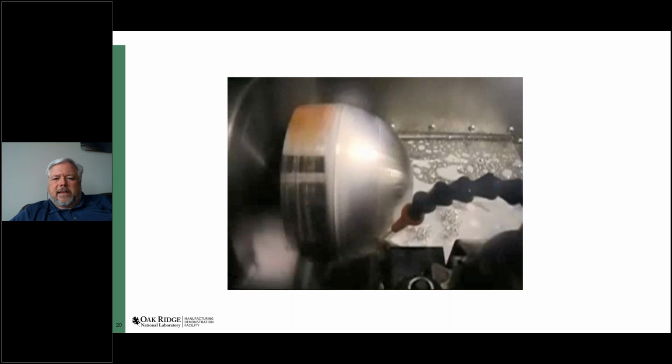Okay, so now what's the price that I pay for this, right? The NC program is getting a lot longer, right? If it was just turning on the outside of a workpiece, you know, it would say move the x-axis from here to there, and it's one line of code. And instead, I'm putting in lines of code that specify the motion of the tool back and forth. And so the program got a lot longer. But mostly the controller can handle that. That's not really the limitation anymore.